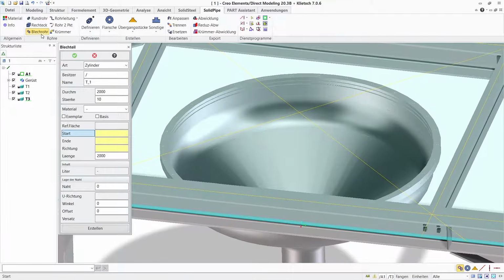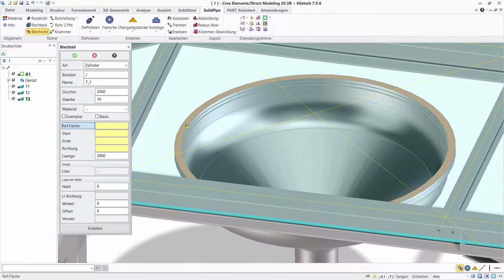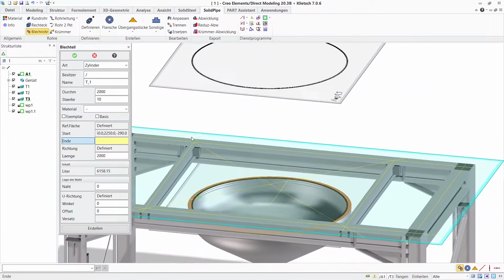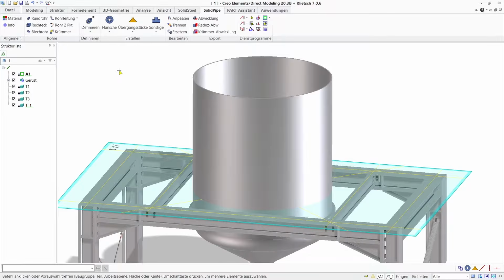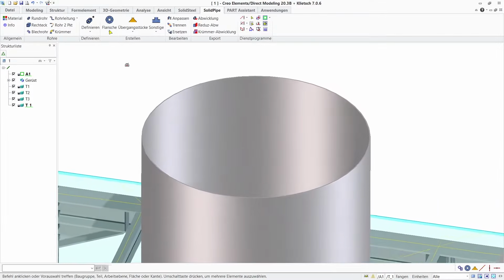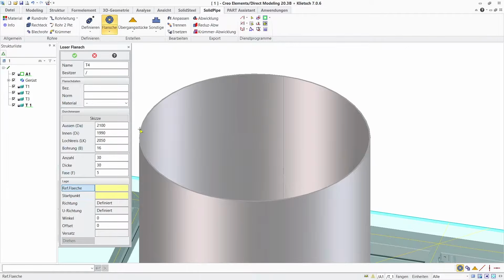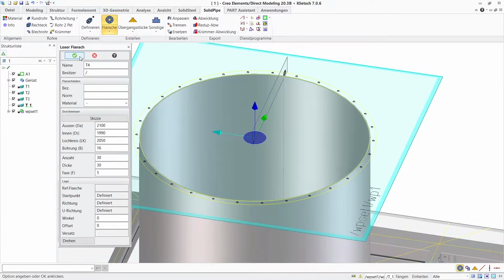We create a sheet pipe with the tool of the same name. By clicking on the upper flange we define the starting point of the pipe and directly get the associated sketches that show start, end points and the geometry. The end point was defined here by the length input in the menu. After confirming, the tube appears and 2 further flanges are of course also added here in order to be able to screw the top on.